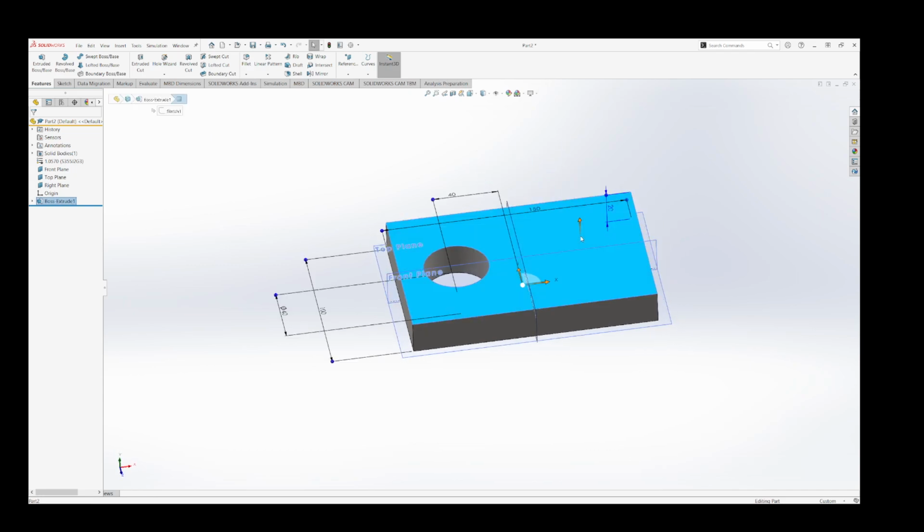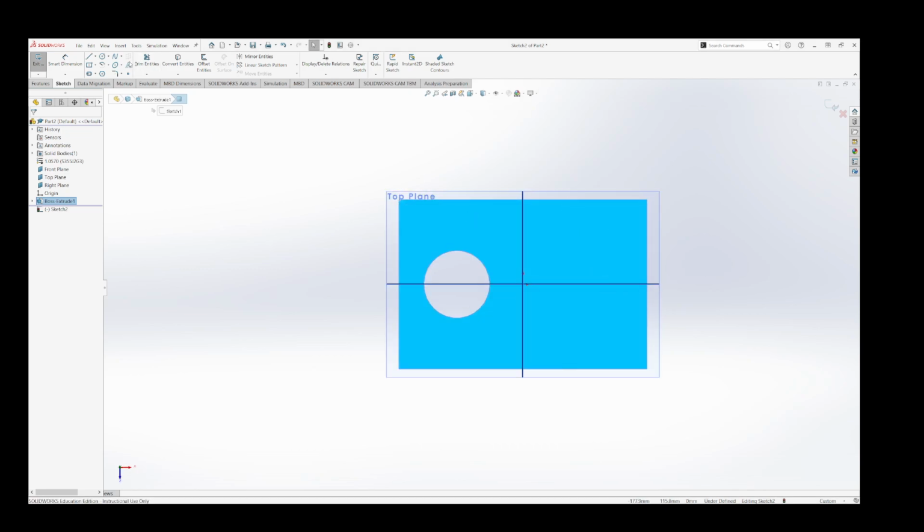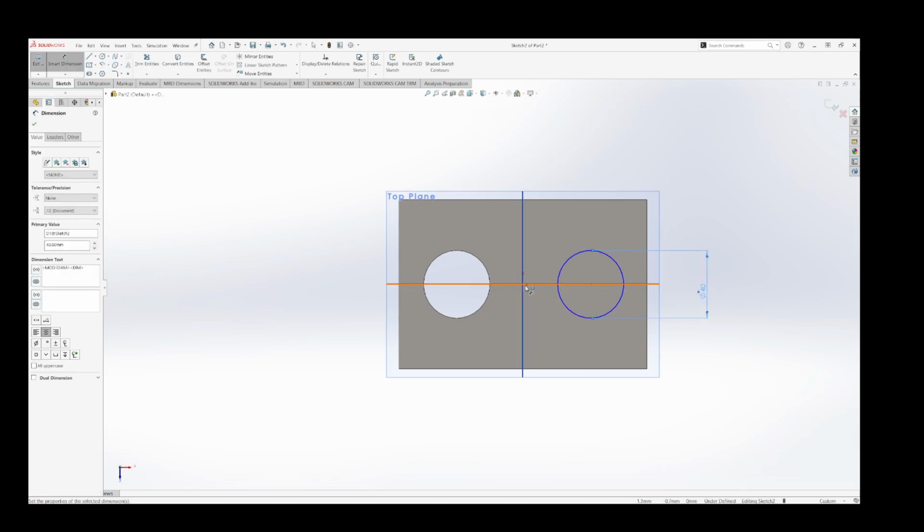Next thing what I could do is to create here the round cylinder on top of this plate. I start by clicking on this face and I see this little toolbox where I can find the sketch. I click on sketch, I click spacebar. From here I go to normal to and then I have the view directly from top of this plate. I choose the circle tool, I start the circle on the surface, I draw the circle, I define this has to be 40 millimeters, like so, and define the distance from the origin to there. Let's say it's also 40 millimeters.